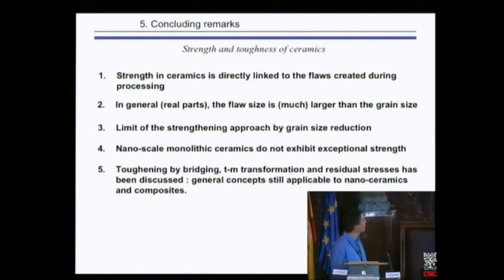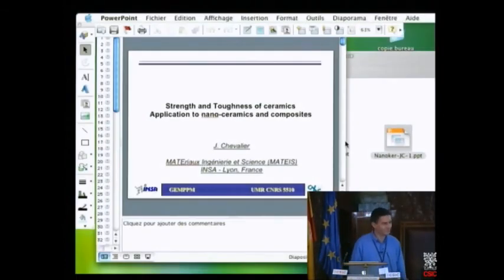But playing with nanocomposites, then we can have some toughening, also by bridging. Phase transformation toughening, also applicable. And also, I will discuss in my second talk about the effect of residual stresses. So that's all for this talk.